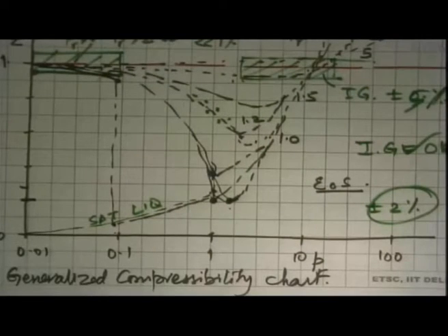So that's what the reduced pressure and temperature help us with: we get a common set of pressures and temperatures for which we can compare various different types of materials. Just by looking at their absolute properties, we get very funny looking pictures, which are very difficult to generalize. So that's why we do this.